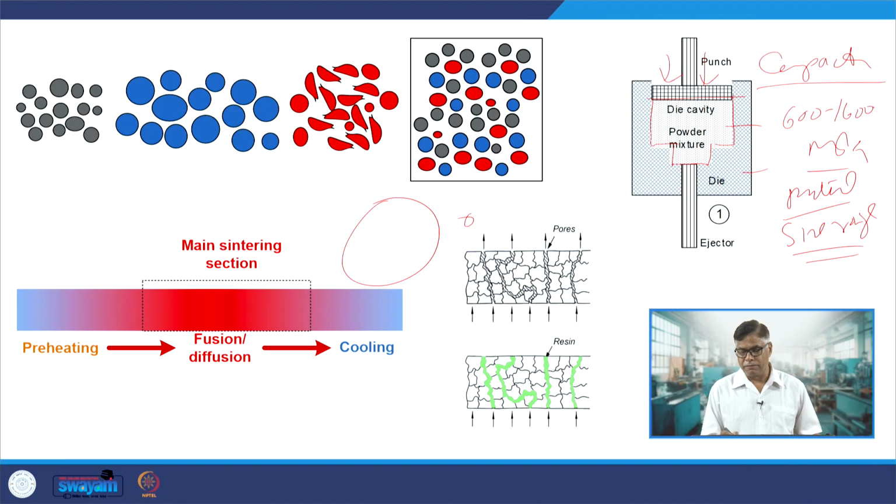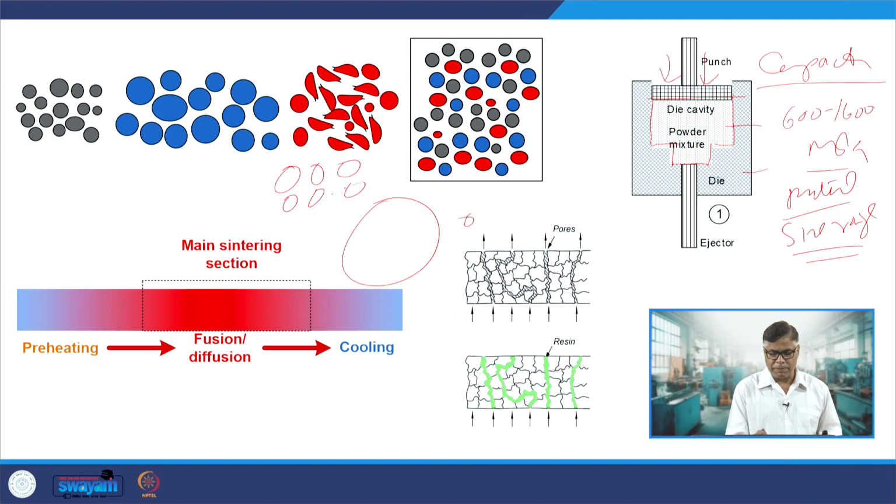And that is important because powder needs to bond with each other first in the solid state at low temperature. That is realized through the plastic deformation of the powder particles. So, say these are the multiple powders; when these are pressurized, they will get deformed and mechanically interlocked like this, and will produce the general shape.